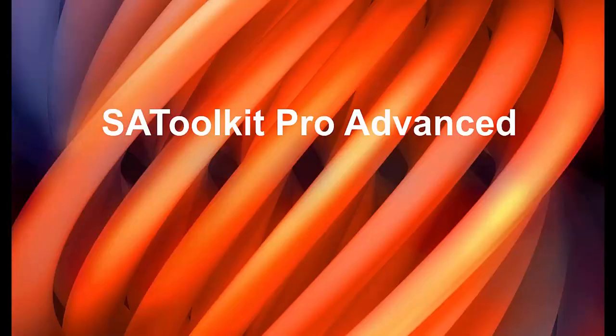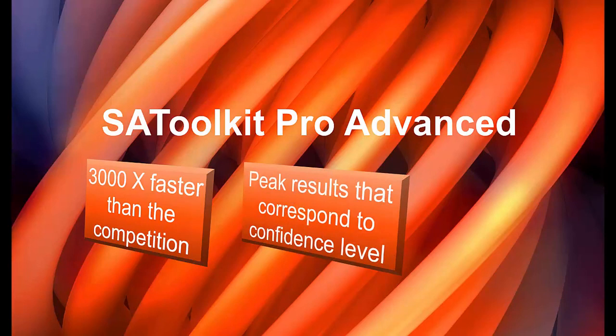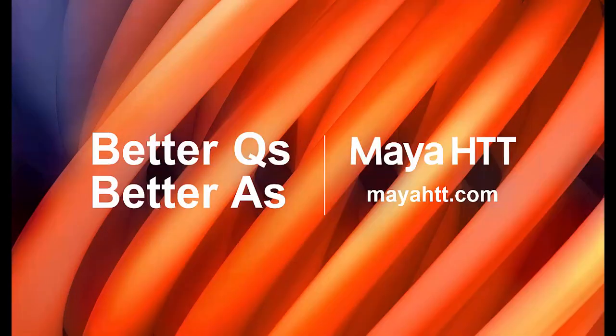In this tutorial, I showed you how to perform a random base excitation simulation of a medium-sized spacecraft model using SA Toolkit Pro. I used its random processor that is 3,000 times faster than the competition, which produces peak results that correspond to the desired confidence level, including phase-consistent vector magnitudes and von Mises stresses. I validated the notching of the input PSD functions in various ways.